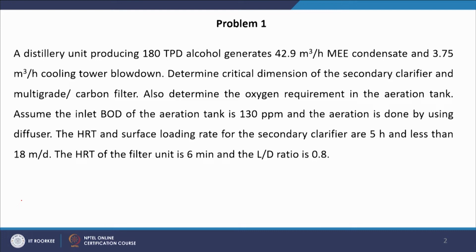The HRT and surface loading rate for the secondary clarifier are 5 hour and less than 18 meter per day, that is meter cube per meter square per day. The HRT of the filter unit is 6 minute and the L by D ratio is 0.8.